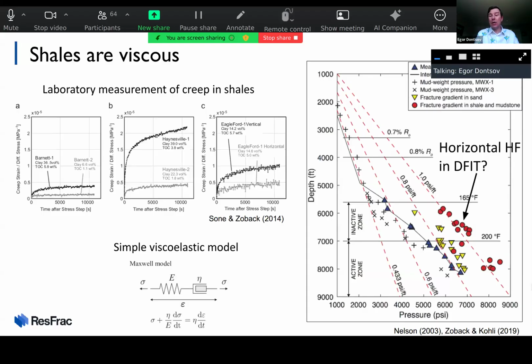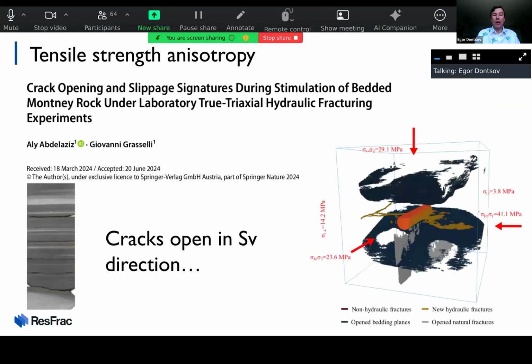So you can see your average stress state could be normal faulting, right? But locally in shales, you may have very high stress relaxation rates, so that your SHmin is almost equal to vertical stress. I say almost because it's all a time-dependent process, and now you have tectonic movement and so on. So this is not perfect, but it's approaching it asymptotically.